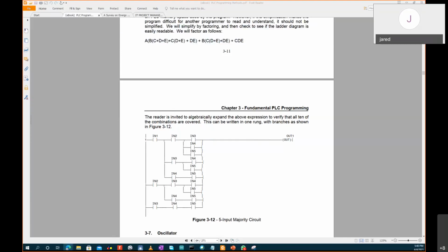If things become a bit complex, you can approach it the way I've showed you with the 4. If you start with the 4, you put the others as don't care, and you first minimize them.